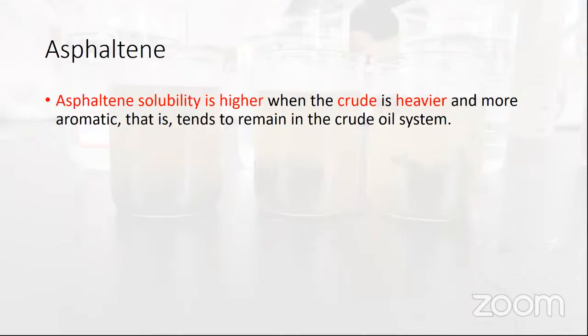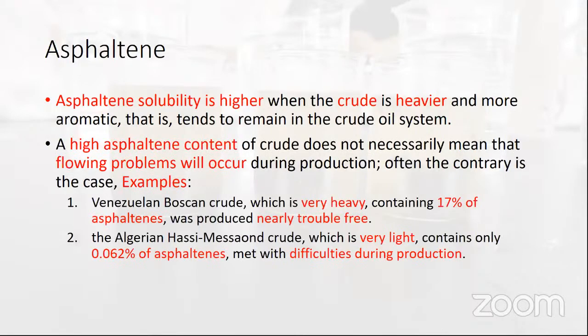So by this interpretation, we were guided that we should isolate the heavy oil interval from the light oil interval. Again, the high asphaltene content doesn't necessarily mean that we will have a problem of asphaltene, because by using the rule that asphaltene will deposit only when we add light saturate components. So the amount of asphaltene existing in the fluid is not the criterion that we are searching for, but we are searching for the equilibrium between the asphaltene and the other components.